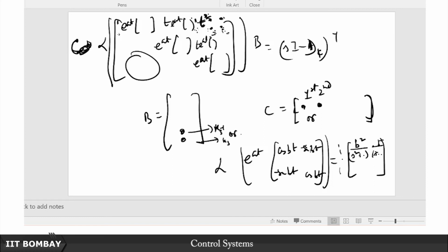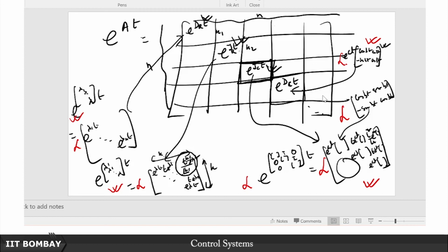So if you don't pick out any of these 4 entries from this block, then you will be missing out not just 1 degree, but you will be missing out 2 modes at the same time. But if you pick out any one of them on the other hand, then you will have some hope of carrying forward this second degree denominator from this 2 by 2 block. Now by the same token, as we've done earlier, the same argument holds for all these blocks that we have seen, for the condition for minimality.